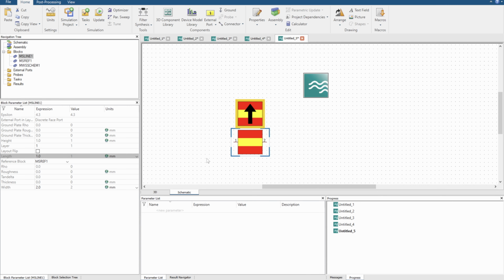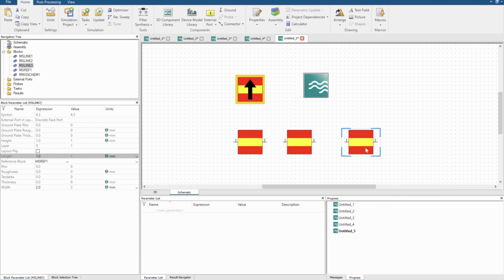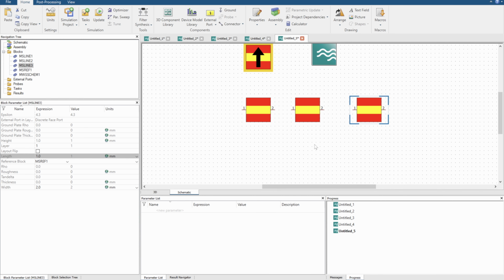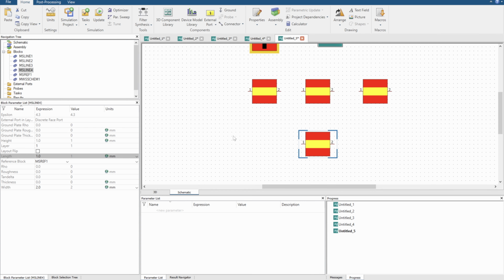So schematic tool, here we are. Now I want to do a third order system and I want it centered around 5 gigahertz, let's say today. So I'm going to create another network and I am doing an impedance match to, let's say, 250 ohms again.